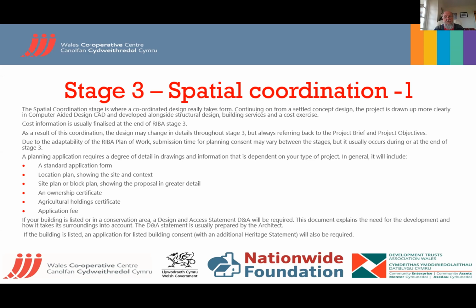If it's in a listed building or conservation area, which a lot of community sites are, you would need what's called a design and access statement. And it explains why it's required, what the design is, what the ecology is, what the impact on transport is, and how it meets the local plan and the development plans.